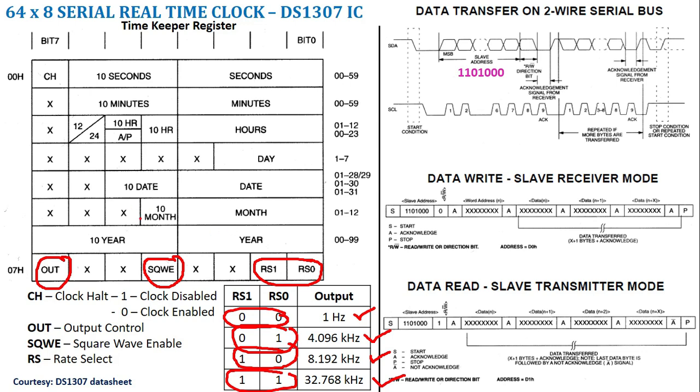So in the RTC part, only 8 bytes are used. The remaining 56 bytes are used as general purpose RAM. Now let us talk about the communication point of view. I have this information in the RAM memory. So this information should be sent to your microcontroller upon request.